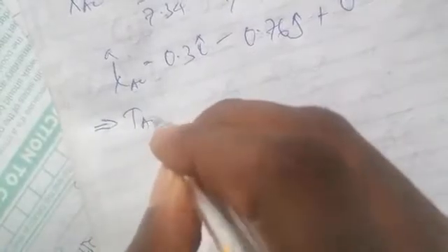So that implies the tension in cable AC, the position vector of the tension, is simply the magnitude of the tension in AC times the unit vector in cable AC. The magnitude was not given to us, so the tension vector in cable AC is simply T_AC multiplied by the unit vector, which is 0.3i minus 0.76j plus 0.57k.